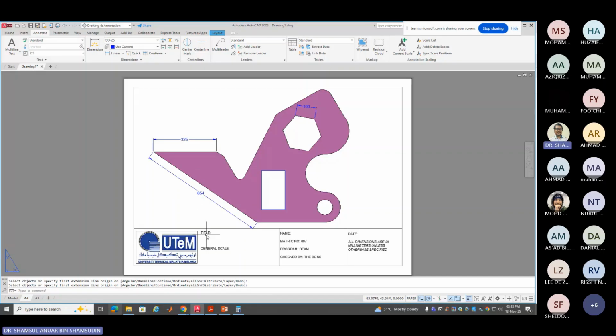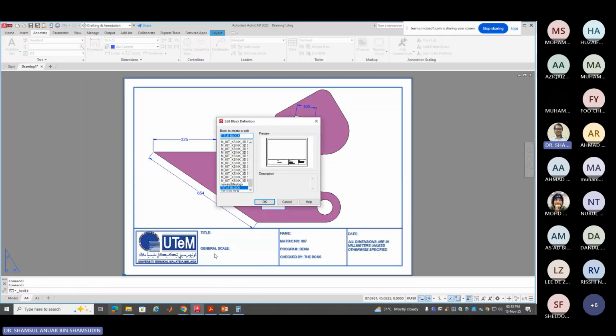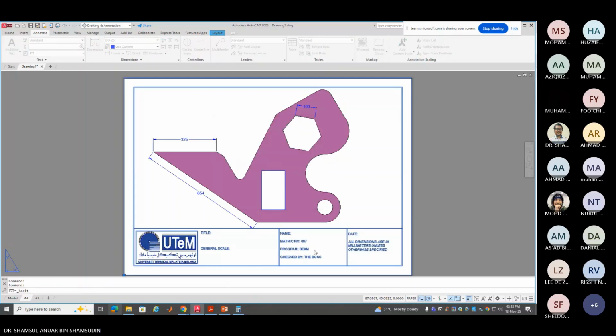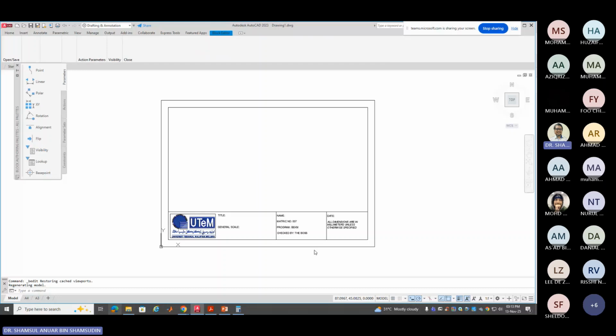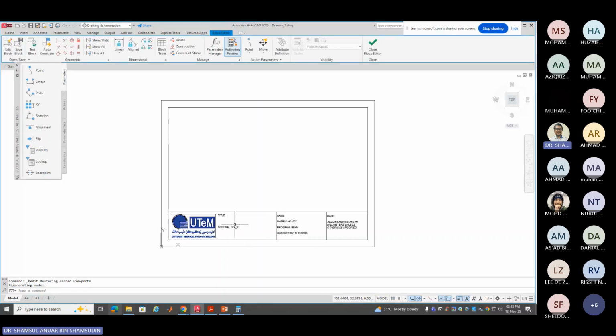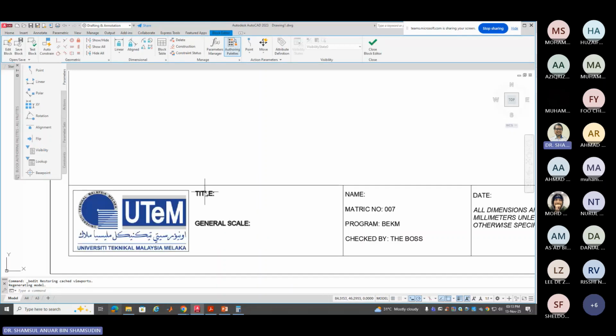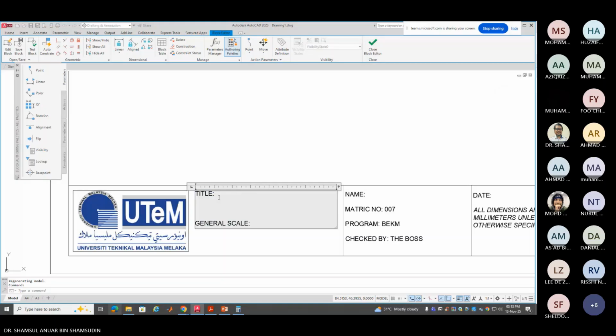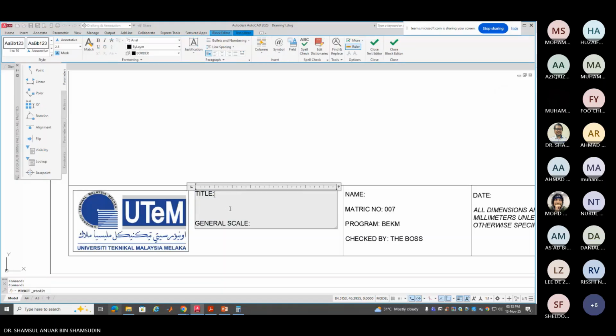All right. Then for the title block, if you need to fill out the information, you can double click. One way is to edit it. So you can go edit here, and maybe add here, homework 0.